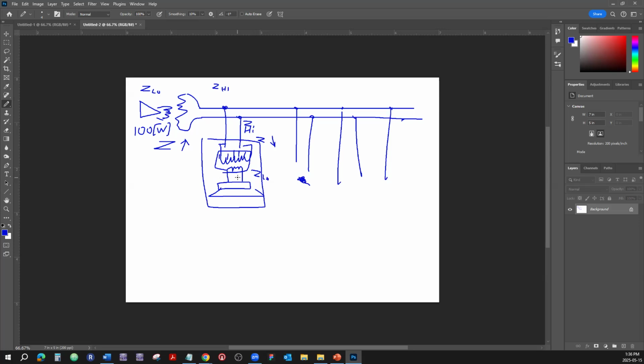And they're never going to be labeled exactly. You know, the tapping that we consider 1 watt is going to be maybe 1.25 watts, something like that. Let's say it's a 1 watt tapping. What does that mean? It means that at the full strength of the signal coming out of the amplifier, when we tap that, which is going to connect just one common to the one, and the other one, let's say we're tapping it at 1 watt and connected to the other conductor of the main audio bus, at full volume it is going to use 1 watt of power. And it's going to pump the music out with the strength of 1 watt.